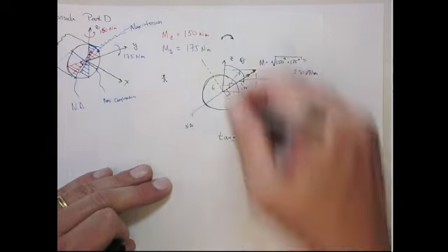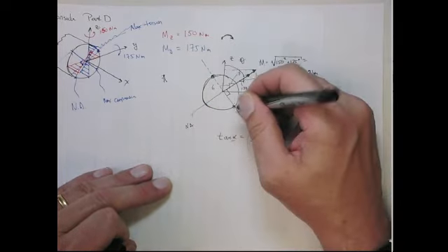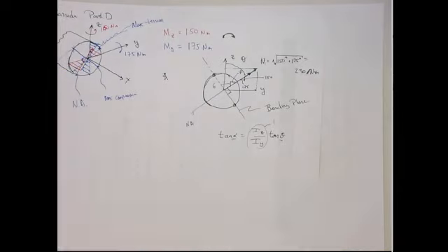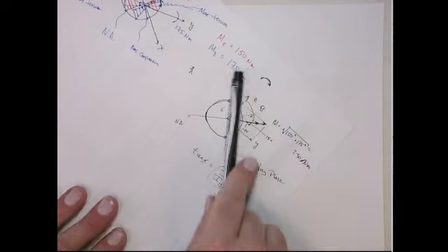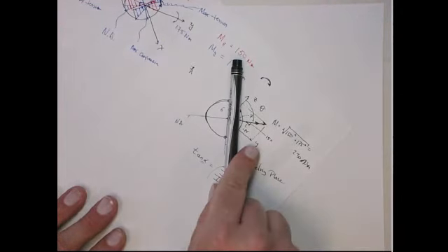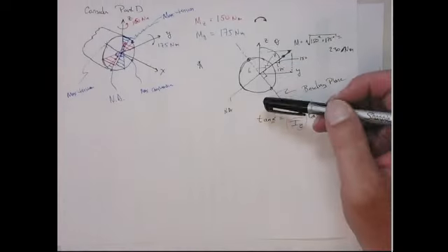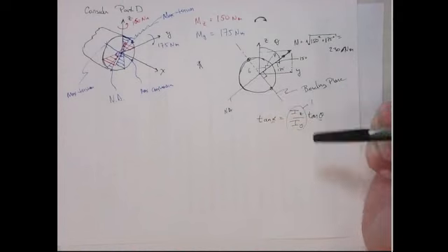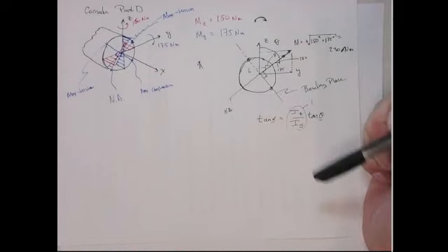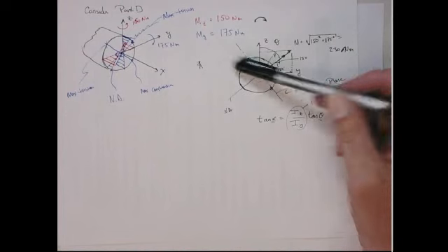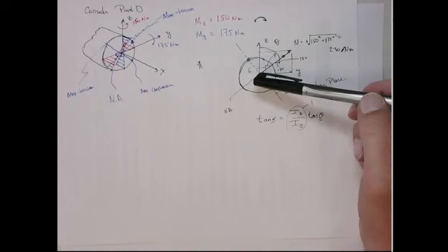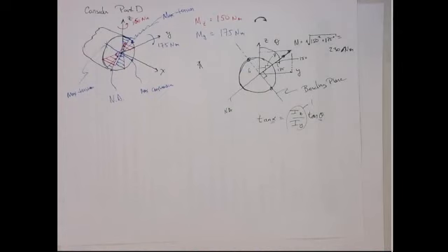All right? And so that means the maximum stresses are going to occur here. Or in other words, this would be just the same as if I considered a problem where I call this the y direction. Okay? If this were not a symmetric cross-section, if it were like an I-beam, that would be a little more complicated, all right? You have to go back and find out where the neutral axis is and then use that to determine where the maximal stresses would be, okay?